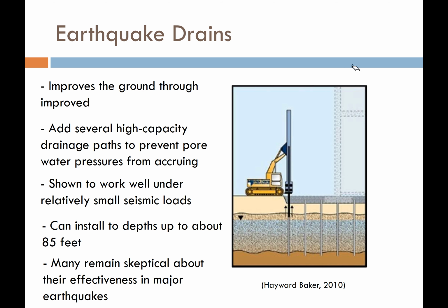And they put these pipes down into the ground. They don't really drill them. They actually just push them down into the ground with a mandrel, and then the mandrel comes back up again. So it's similar to a wick drain. So installing them can be done very, very quickly. And the idea is that we're going to improve the ground, remediate against liquefaction by improving the drainage.